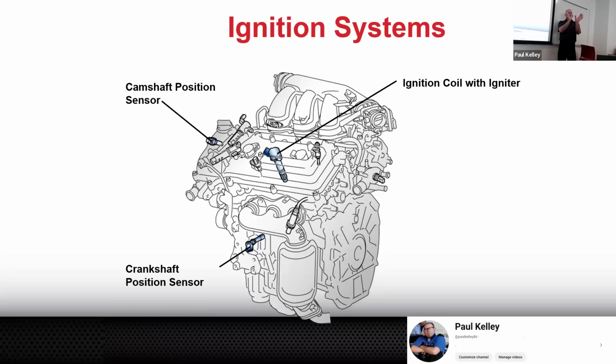So they would pick a cylinder, let's say in this case, cylinder 3, and they'd line up all the piston rings. Your piston rings come around, there's an end gap right here, and at that little gap, compression leaks out. So you put one here, and you put one here, and then they're always going to be offset. Well, if you line them right up straight, it'll lose compression. So these cars with 0 miles would come off the line and they'd be misfiring, and they'd be like, oh, well, maybe it's the cap and the rotor and the spark plugs and the wires and whatever. And then they do a compression test. It's got low compression.